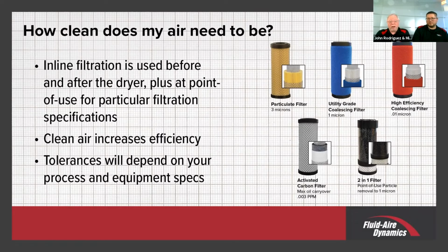So it would bring you down to 0.003 ppm, which is virtually oil free. The problem with charcoal filters is there's no indicator of when they're used up. So you have to get a feeling for how much air you've run through that filter and how long it will last. Generally speaking, all the filters need to be changed once a year.